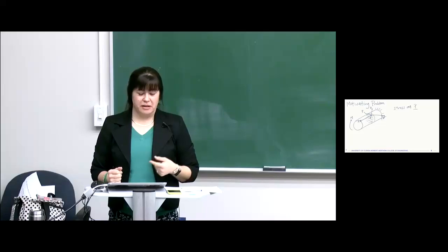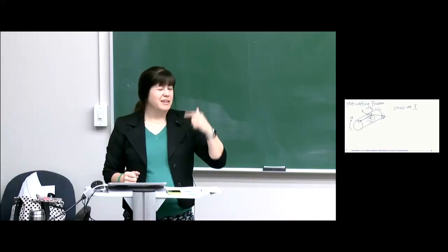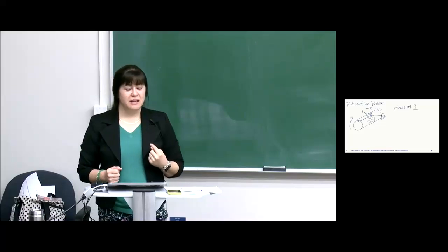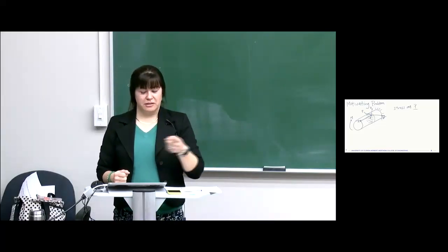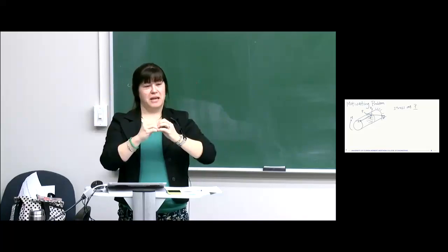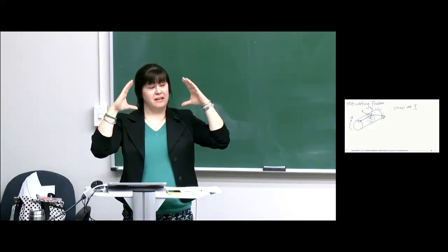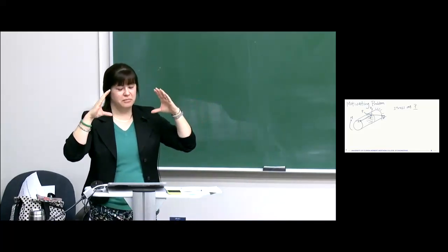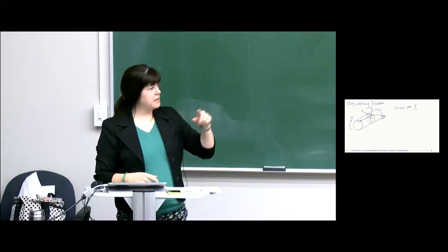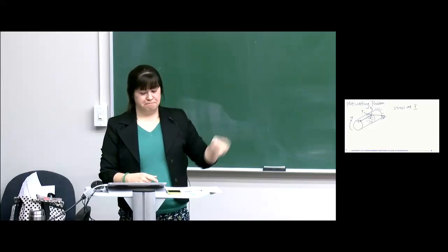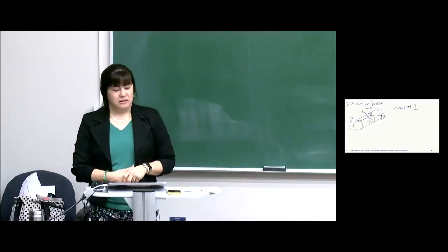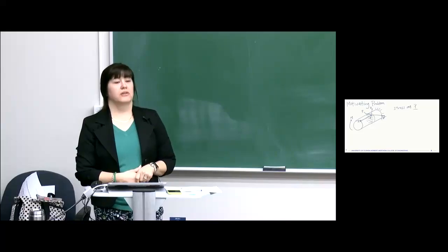And if we think about equations, we remember maybe something like TR over J. That would be the shear stress throughout the bar, where R is the radius. And if we're at the maximum radius, shear stress is highest. And so the maximum shear stress in this cylindrical bar is at the exterior of the bar, at every location.